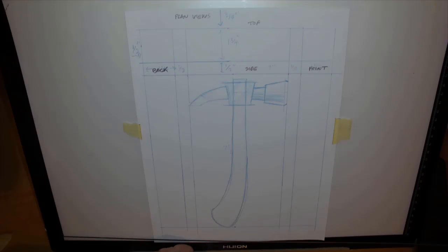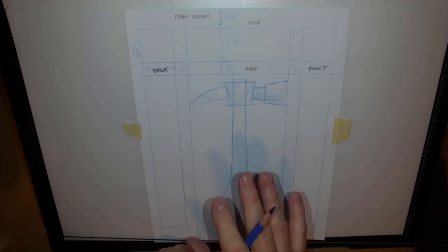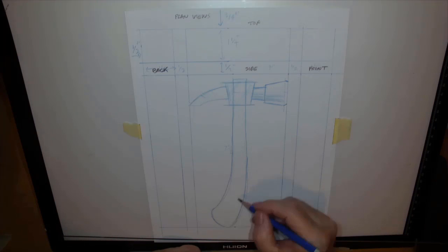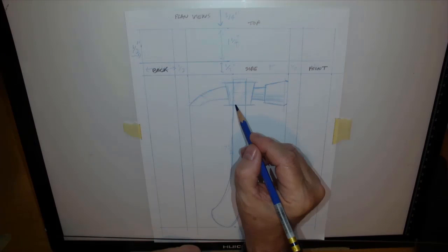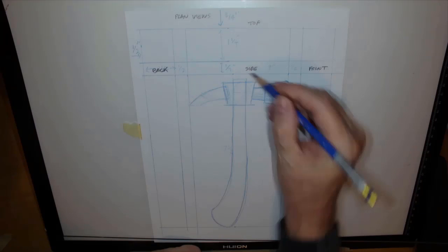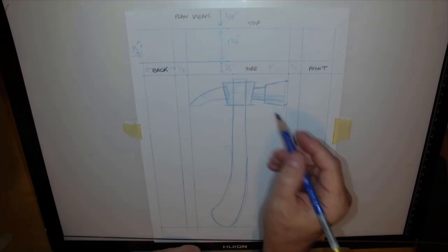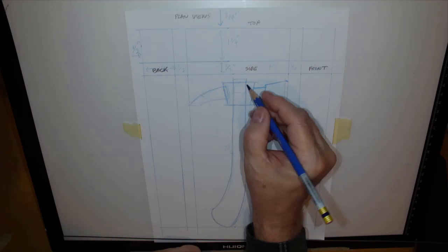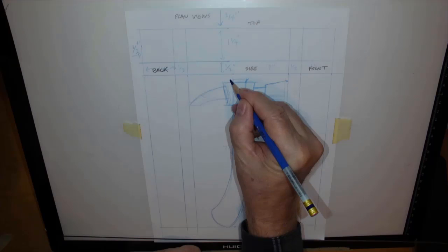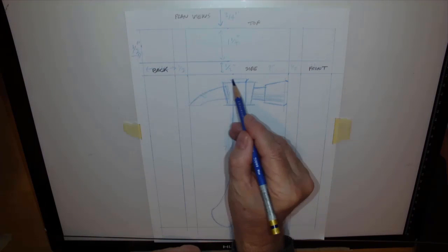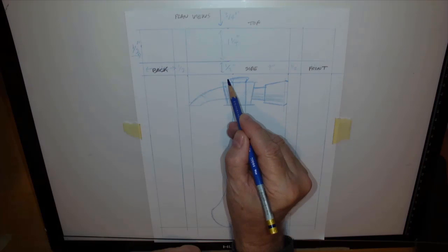Now, functionality, here's what's important when we're designing a simple prop: what are the materials and what's the construction like. So analyzing and doing some research is good. If this is a wooden handle coming up through a hole that is bored through the metal that creates the head of the hammer, the wood would come through, and then you would hammer that down to fray the edge so that this heavy metal won't go flying off the edge of your wooden handle.